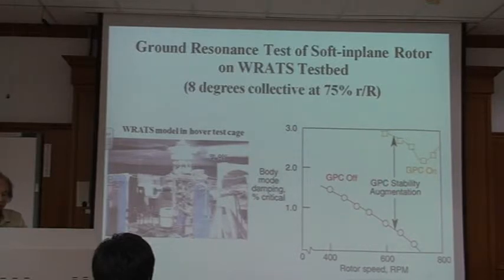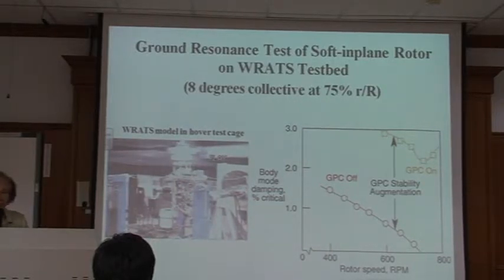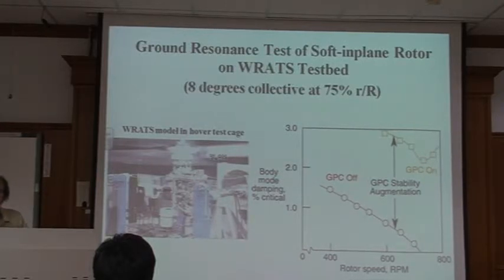So if you cross this line, meaning 0 damping, you get negative damping, and the whole system becomes unstable. So if you don't do any control of this spinning, they oscillate with the wind, the oscillation amplitude gets larger and larger, and it will break the wing.